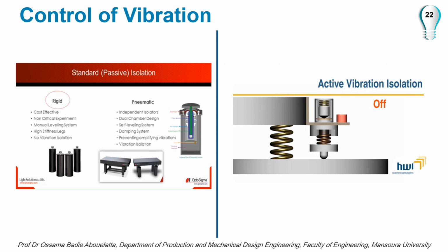We call an optical table without pneumatic isolation rigid. This is damped purely via the mass. We call a table with air suspension a pneumatic table. Both are passive vibration isolation systems.